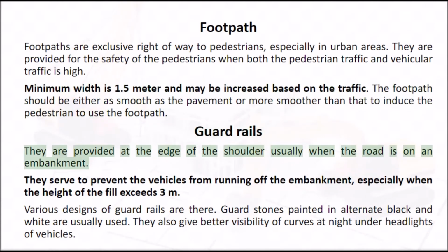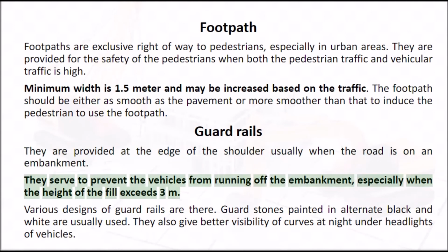Guardrails. They are provided at the edge of the shoulder, usually when the road is on an embankment. They serve to prevent the vehicles from running off the embankment, especially when the height of the fill exceeds 3 m.